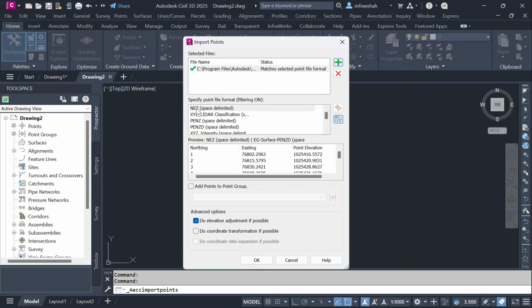Here is northing, easting, elevation. Is it the correct one? No. Look here. It reads northing, then easting, then elevation. Look, for northing, it takes the point number. It follows the order. You tell it the first column is northing, it takes the first column as north. Second column is easting, it takes the second column as east.